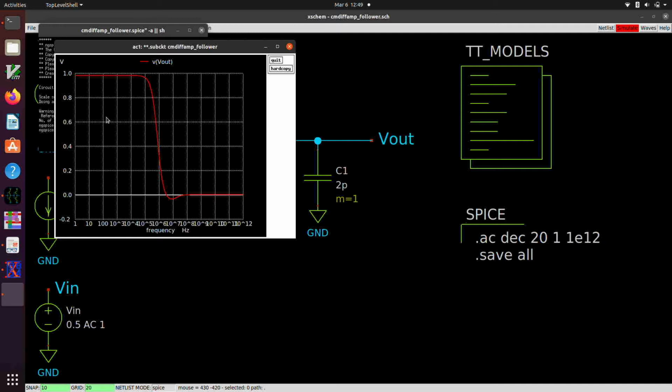We'd like to see more like a Bode plot here, but what we're actually seeing here is probably the real component of the output voltage vector, because the output voltage vector actually winds up being complex in this type of analysis because it's a linearized analysis, and we have sort of magnitude and phase information, and that actually comes out in a real component and an imaginary component for the voltages in the circuit. And so that's not quite what we'd like to plot.